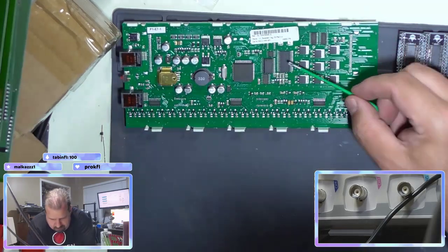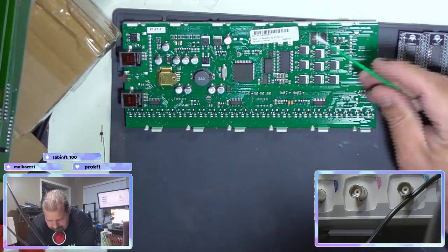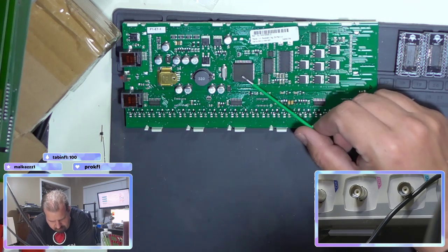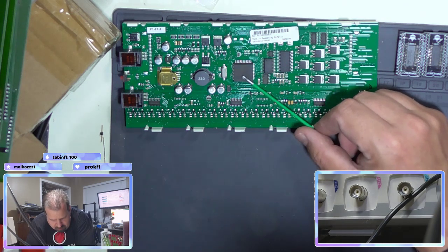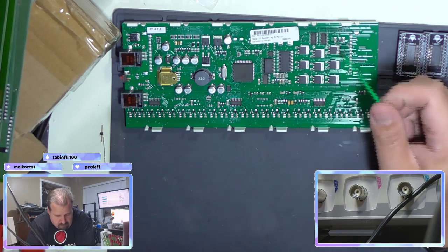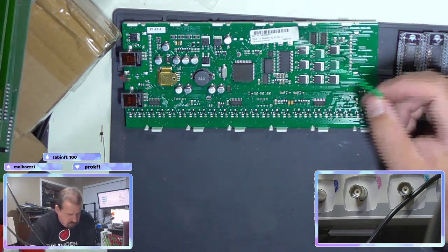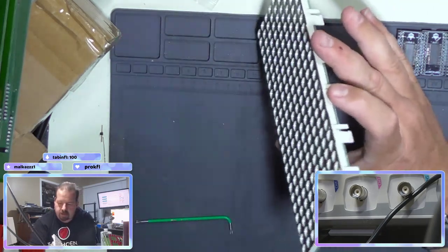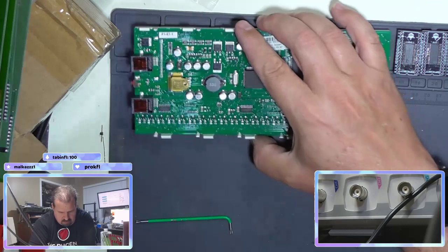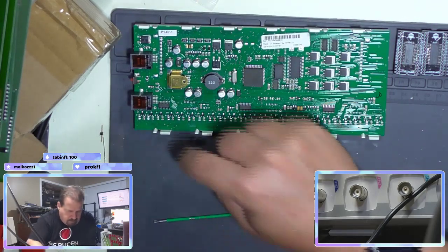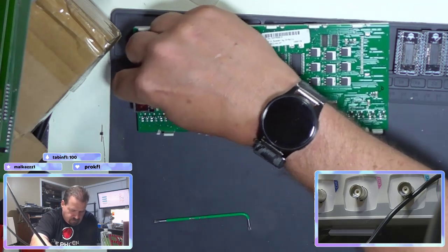I may sacrifice a board to pull this chip off and read it, because this is an 87. I'll look this chip up, see if it's got internal code or external code. If you read the code off the chip, then we can figure out the serial protocol for this. Otherwise, it's most likely RS-485. They're all on a bus, and you probably have to set up, probably press this button when you first turn it on.